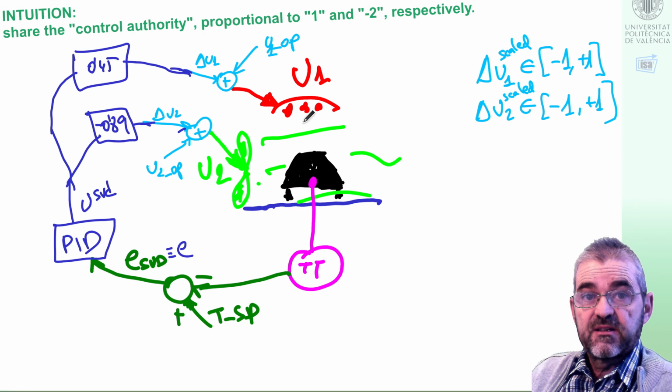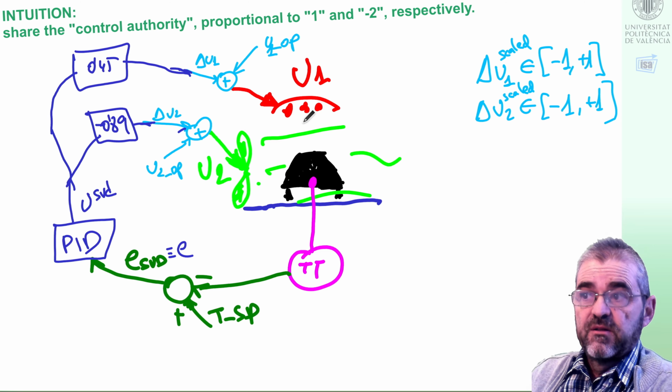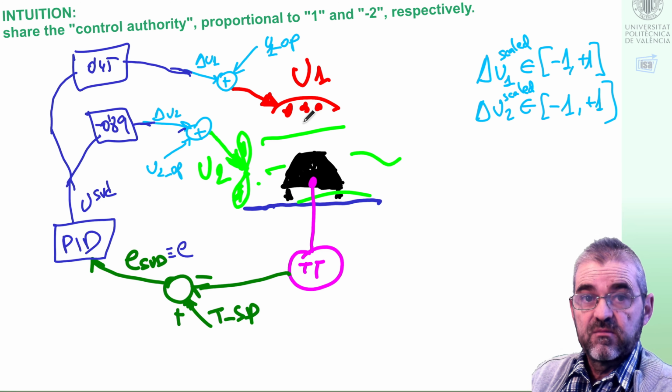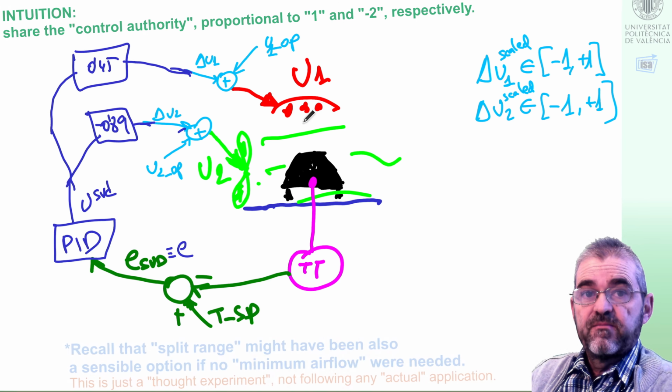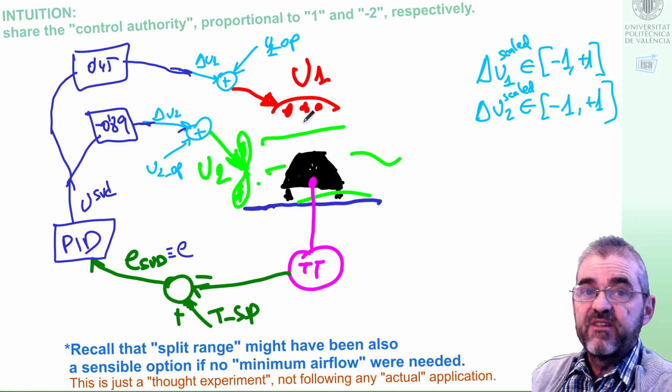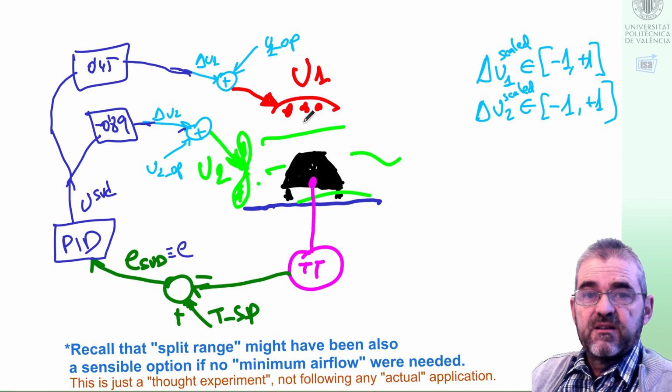But of course, this case is so simple that we sort of could have had the same intuition ourselves. And in fact, this would be a load balancing strategy. I mean, I am heating with the resistor and I am simultaneously blowing because maybe I have some chemicals and I need some minimum ventilation in this process. But the thing is that maybe if I need no minimum ventilation, I could have decided that the operating point is, let's say, resistor at a given power and blower being off.